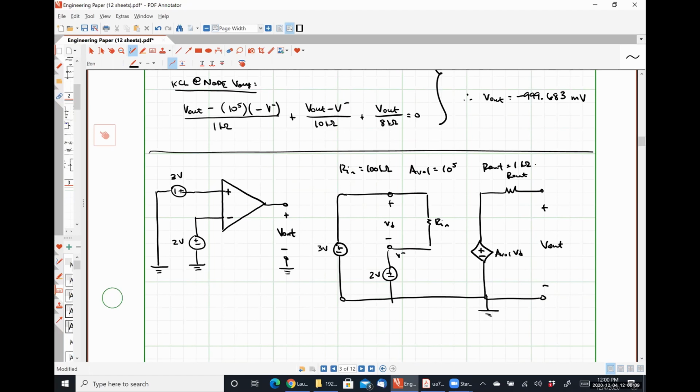So the problem that we have here is that we are not paying attention to one of the topics that we talked about previously in this class: effectively, for an operational amplifier, the output voltage can't exceed the power supply voltages. We're not taking into account how we are powering this thing, okay? We have neglected to do that to this point. We're going to stop doing that, all right?